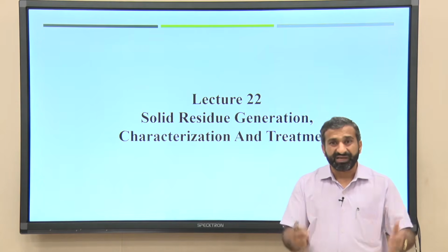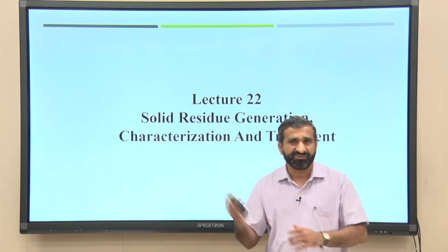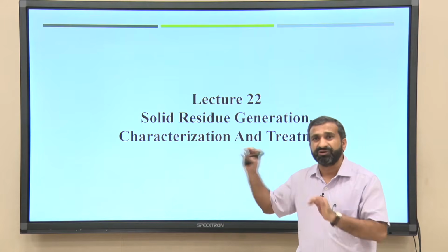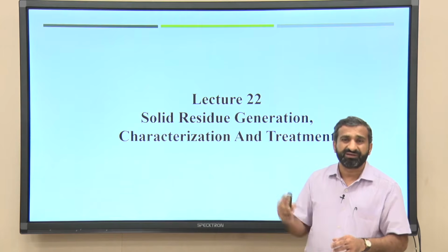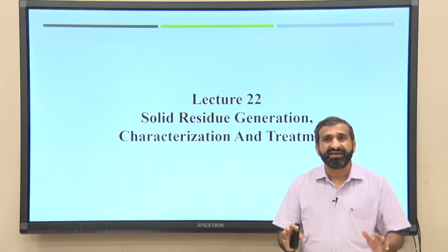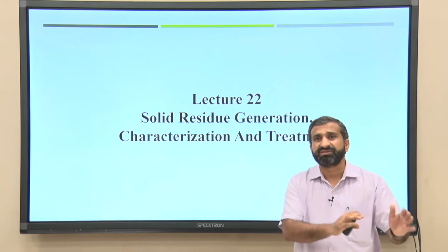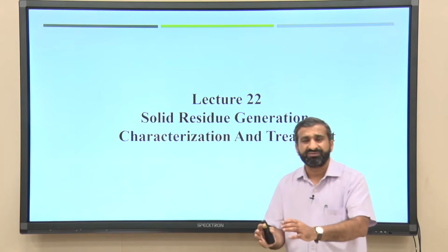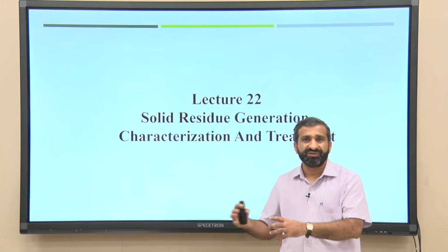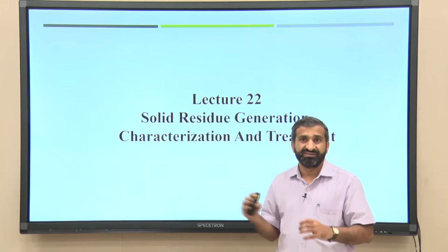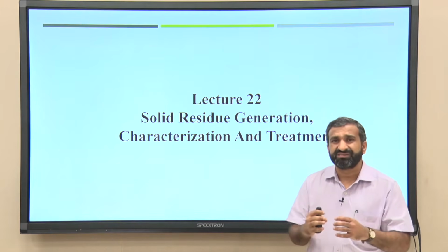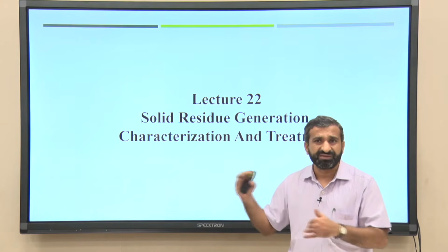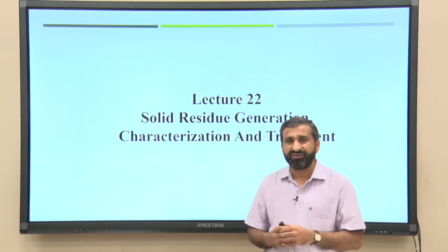If segregated waste is being fed into the incineration plant, obviously the solid residue characteristics will be somewhat usable to produce some other kind of product. But suppose unsegregated waste or some uncombustible matter has been added into the incineration plant. Obviously, that kind of material will come especially into the bottom ash, the slag as we call it, and treatment of that kind of waste is very difficult. Even utilization for some other uses will also be very difficult.